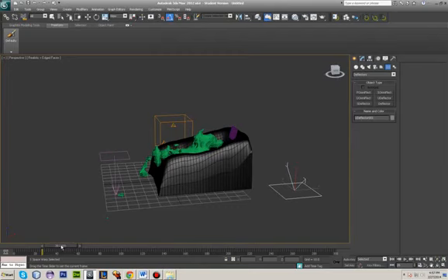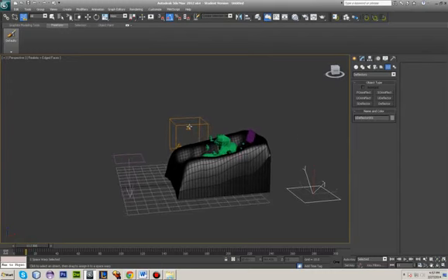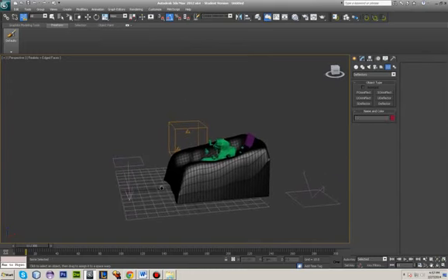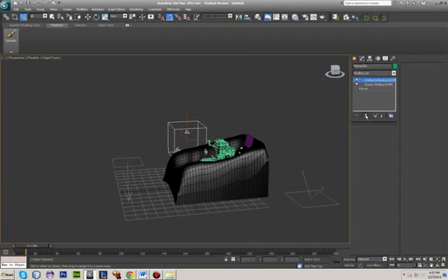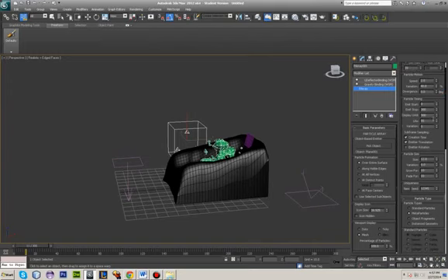There you go. One thing that I see immediately is that I need to increase the life of every single particle because they kind of end here and I want it to flow down. So I'm going to go to P array, modify P array, and then change life to 70 perhaps. That should work. Change it back to ticks, and ooh, I'm still at 100%, that is not good. Change it to 10. And now I can kind of see the behavior.